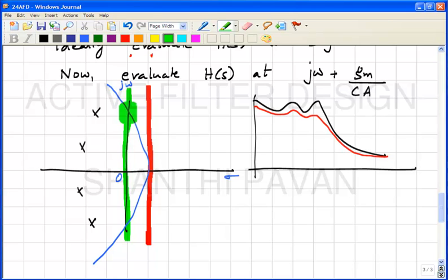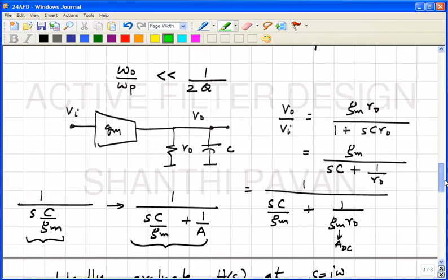Okay. So what is the parasitic pole doing? It is giving you excess phase at the unity gain frequency. Correct? Okay. Now if you have finite gain, therefore if it is compensating, what should it be doing? In other words, excess pole adds phase lag. So finite gain is adding phase lead. Okay. So you can also understand that through this. What is the unity gain frequency approximately?